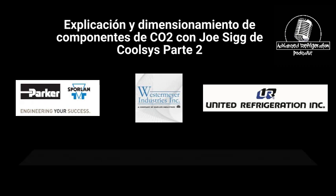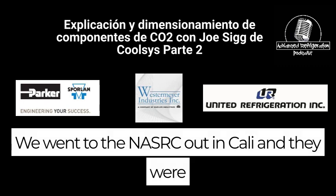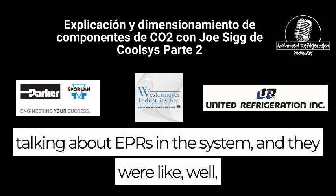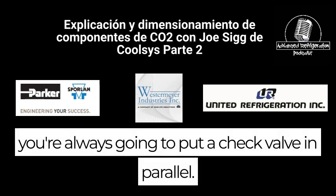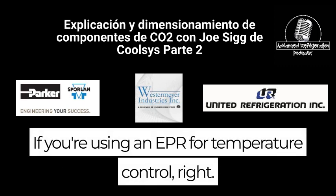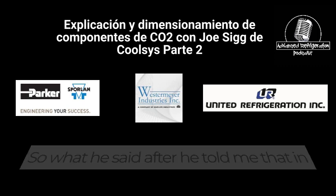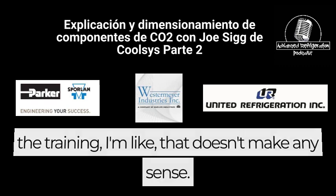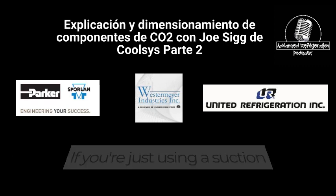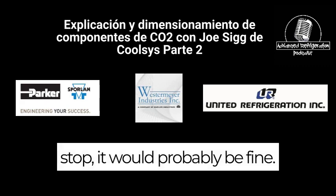I have a question about that. I asked this at the NASRC out in Cali, and they were talking about EPRs in the system, and they said you're always going to put a check valve in parallel. But then I thought about it: if you're using the EPR for temperature control, it's going to make that pressure higher than the outlet, so it's going to start bypassing on the check. I thought that doesn't make any sense. If you're just using it as a suction stop, it would probably be fine.